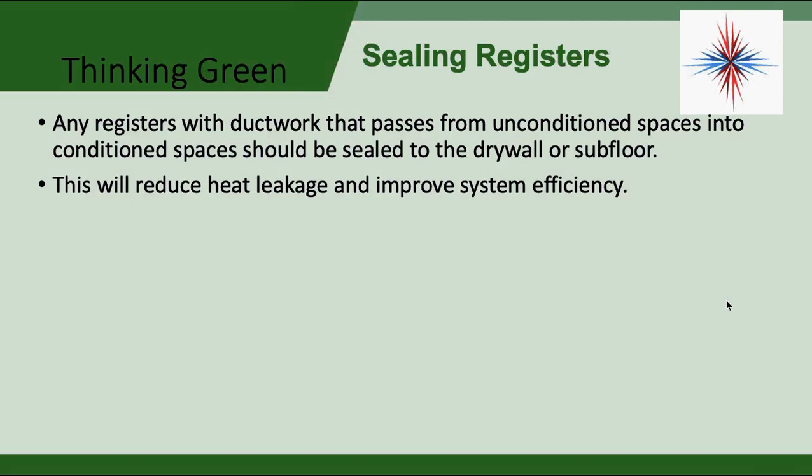So if you have a ceiling register that's coming from an attic, it's required by law to be sealed, okay, so that air can't seep around it. It reduces heat leakage and improves energy system efficiency.